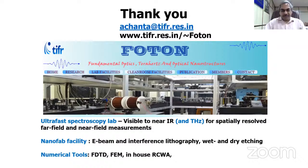Right. The simplest thing I started with, before our clean room was even built in TAFR, was to use two laser beams and make them interfere. You get dark and bright fringes, so you can get a one-dimensional grating, a periodic structure. If you do partial exposure and then rotate your sample, you can get a two-dimensional pattern. There can be circles, there can be squares, depending on the exposures. You can actually manipulate these things. This doesn't require very high-end equipment.